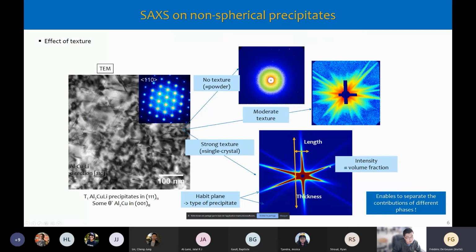In this case, this is the case of laminated rolled sheets, really. These alloys are usually done like this. They have this typical rolling texture, which is brass texture, where the plane of the sheets are actually 110 planes of the aluminum. And because they're 110 planes, as you can see for this TEM orientation, 110 is the viewing orientation, which is the best for preparing TEM samples and observing these precipitates, because two variants are actually